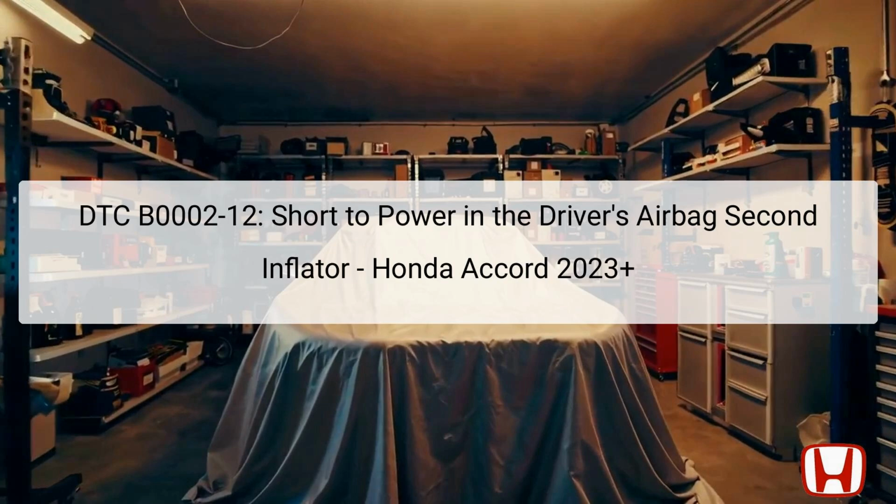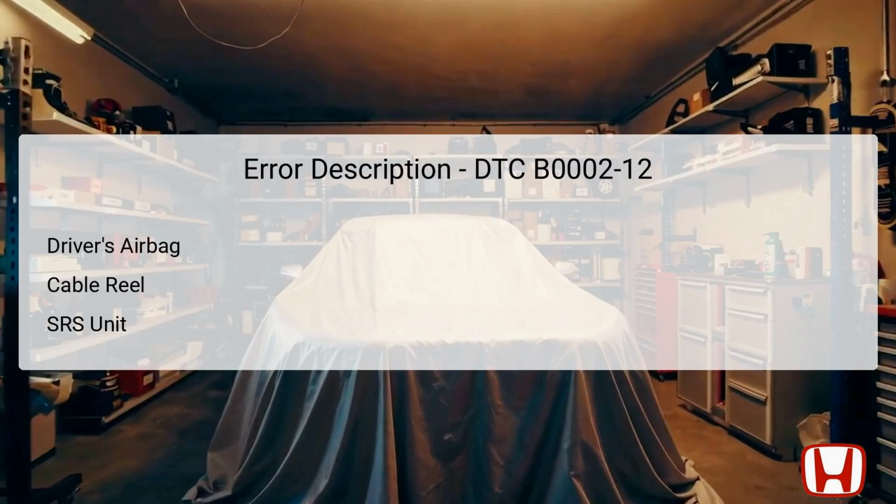It is crucial to handle the airbag system with care, as any errors can compromise passenger safety. Make sure to review the SRS precautions, procedures, and battery disconnection methods before beginning the troubleshooting process. Understanding the components affected by this code, such as the driver's airbag and cable reel, is essential for accurate diagnostics and repair. Failure to address this DTC can affect the vehicle's airbag operation, posing a significant risk in case of an accident.